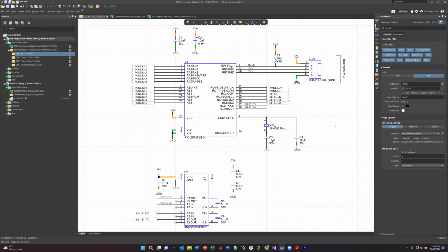it connects through this connector, and all it needs is power and ground, master clear, clock, and data. These specific pins. If I do that, it will program the flash of this processor directly. So that is how code is loaded into this processor, through this port.